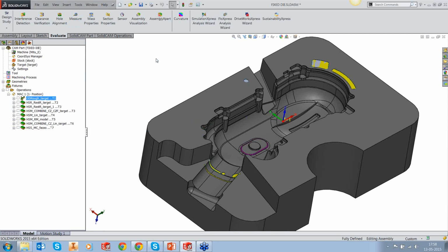So we're talking between 48 and 50 millimeters or 55 millimeters out of holder. For sure, we will not be able to get to all those areas with iMachining, but we can scoop out maximum material using iMachining, provided it falls within the bracket of the tool lifetime.